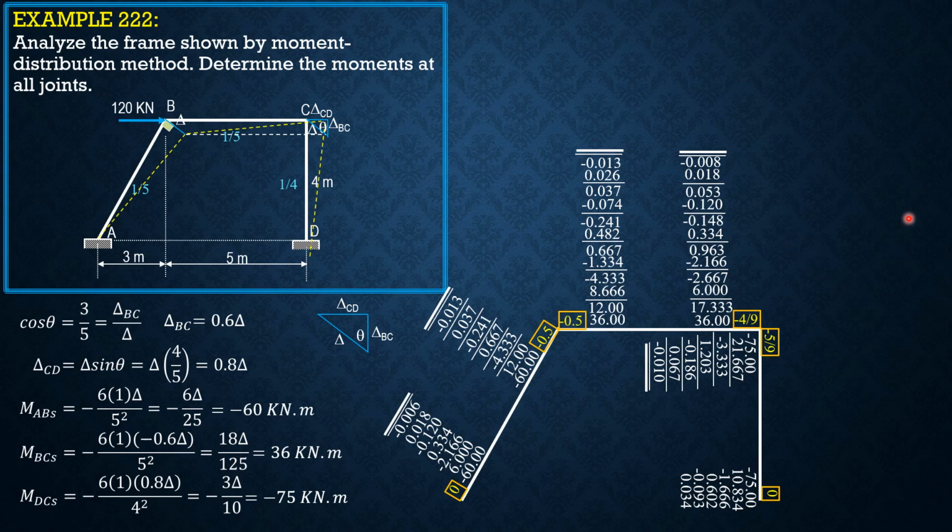And let's assume clockwise moments for MAB and MDC. So Y over 4 equals Z over 5 equals 5 over 3. So Y is 20/3 and Z is 25/3 meters. MAB therefore is negative 55.940 R. MBA is negative 51.883 R.